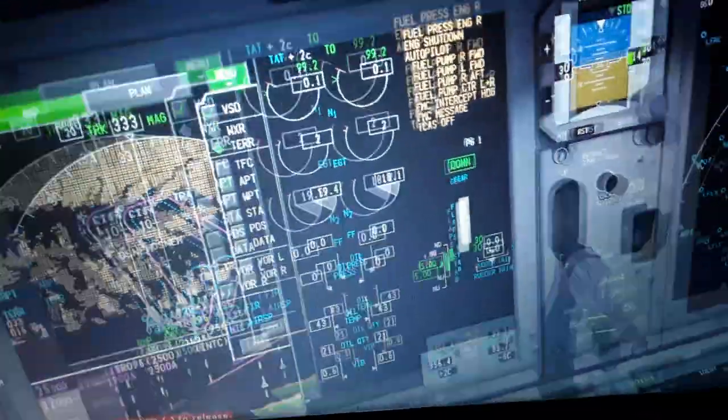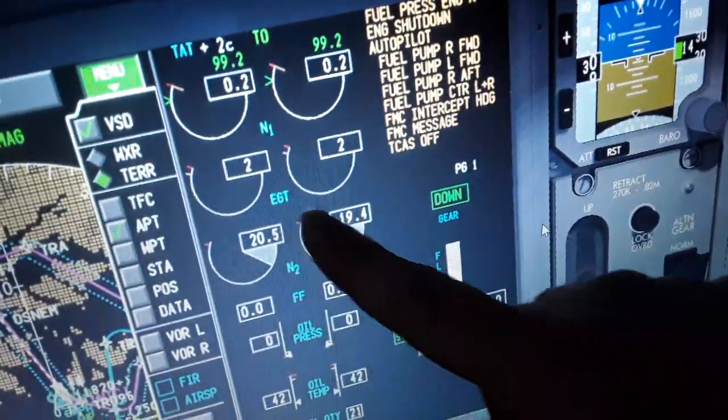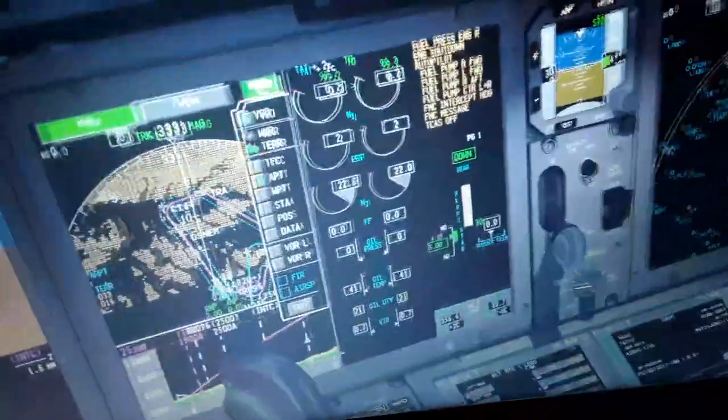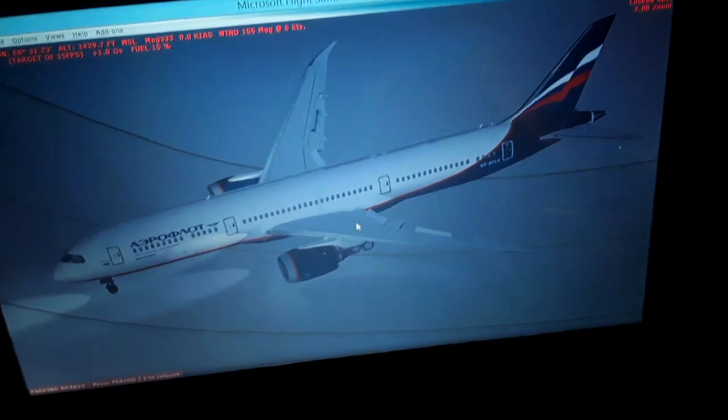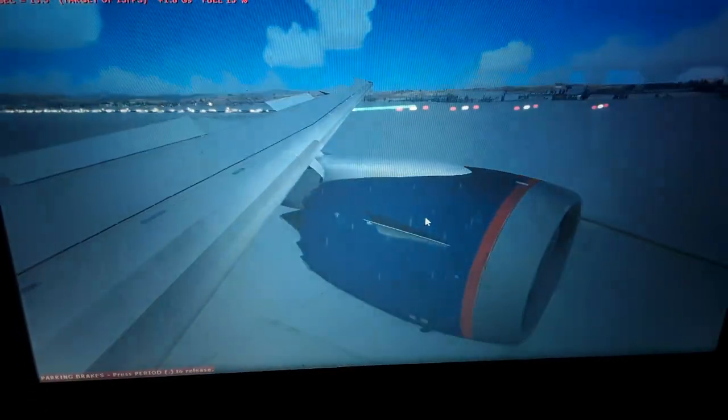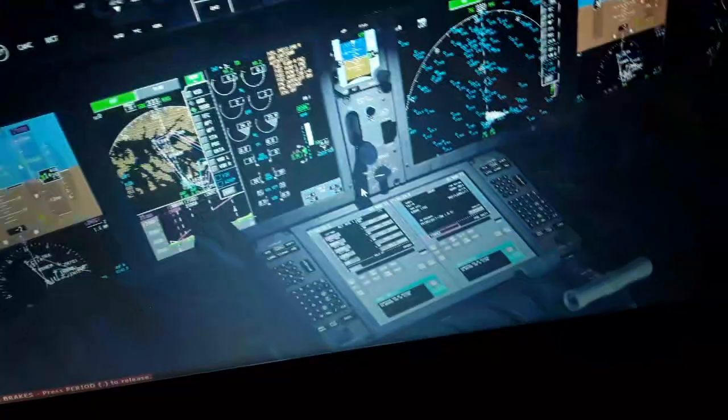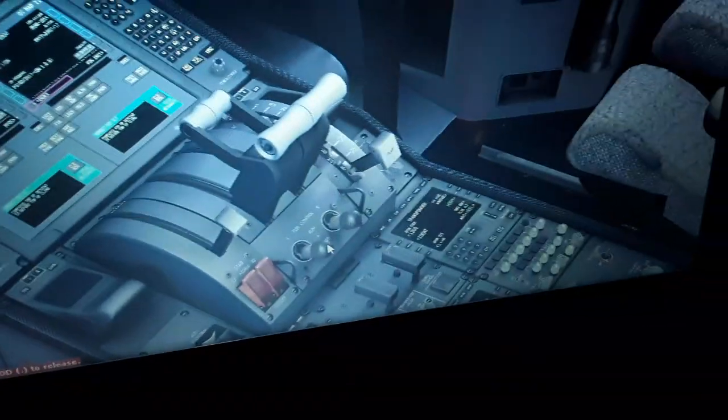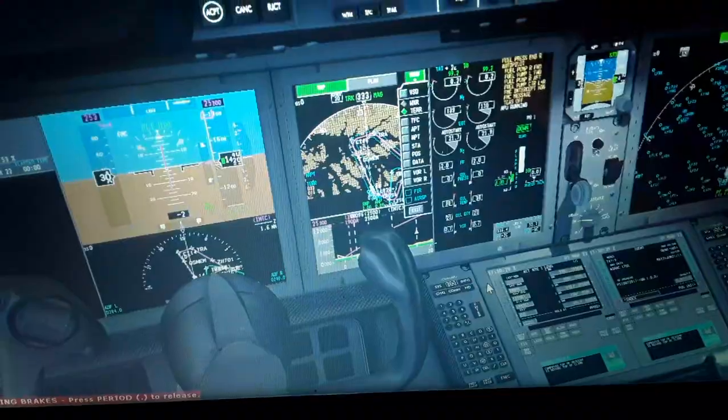So we have pressurized air only from the APU admitted into the engines, two stage. So above 20% we can start the fuel flow. We have 22, so we have pressurized air right now. So we can start the fuel flow here, fuel control, both in the on position.